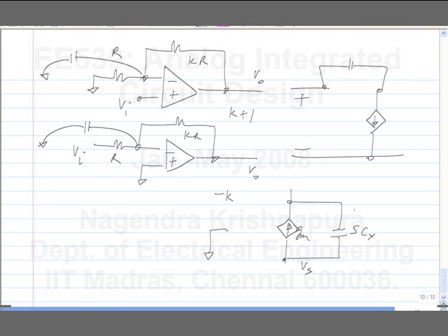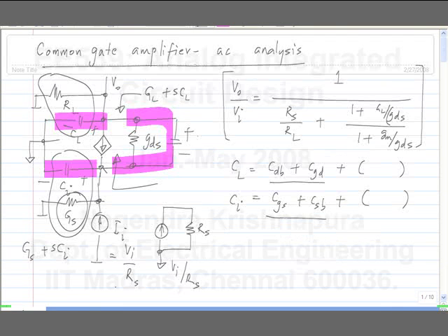The same thing that I described earlier will happen, but in a frequency dependent fashion. If you look in here, at low frequencies, you will see approximately 1 by gm. Because of the capacitance, it will increase at high frequencies. The input impedance will increase at high frequencies. What kind of an impedance is that? It's an inductor, right? It will look like 1 over gm in series with an inductor.